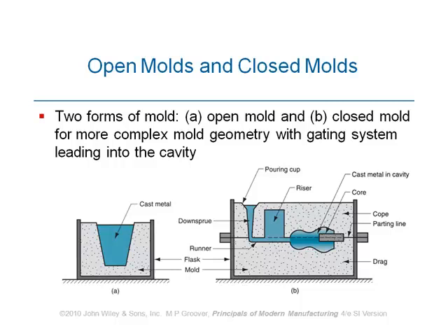How can we deal with this problem then? We are not interested in having bubbles and void spaces inside the material. How do we deal with this? Yes? What's that? Tap. Yeah, it wouldn't help, would it? Well, even if you can remove bubbles from inside, you've got to fill in those bubbles. And those void spaces should be filled in with molten material, right? And that's the role the riser is playing. That's why we have got the riser in place.